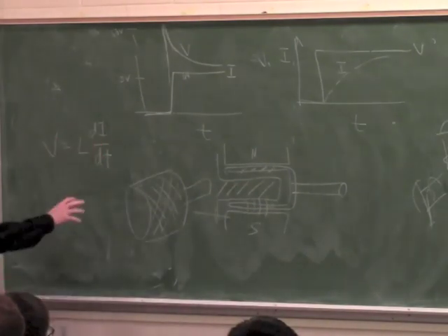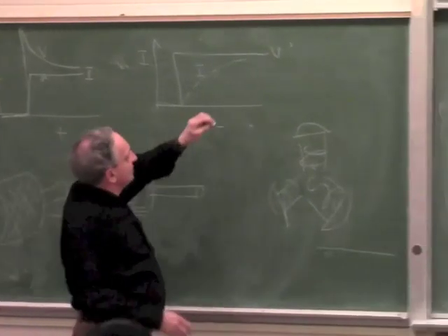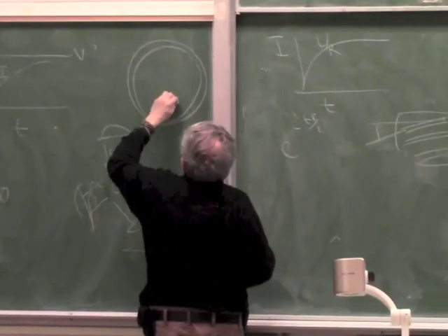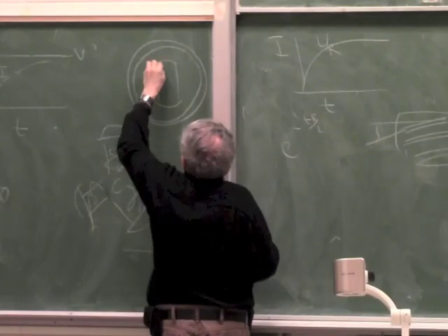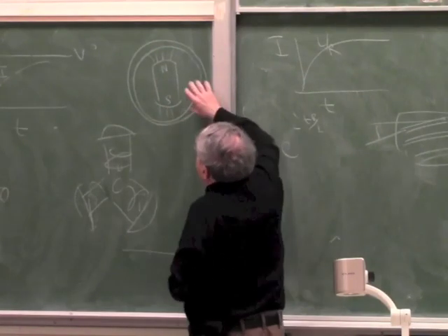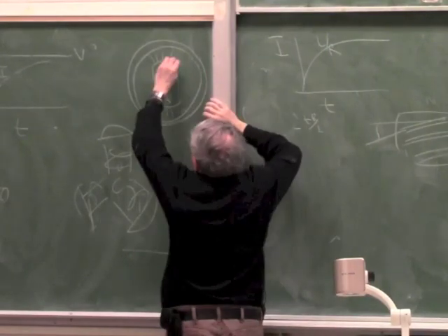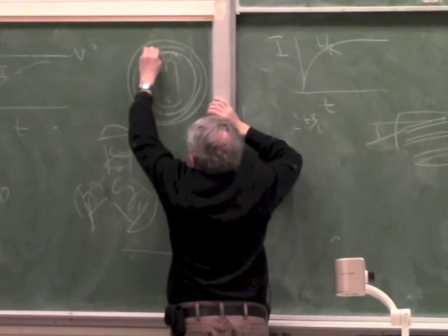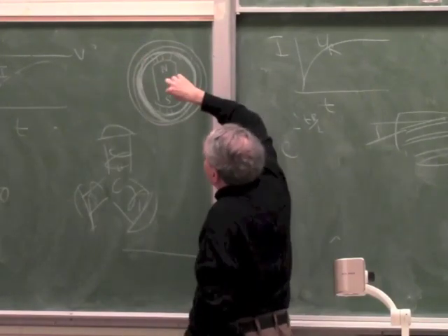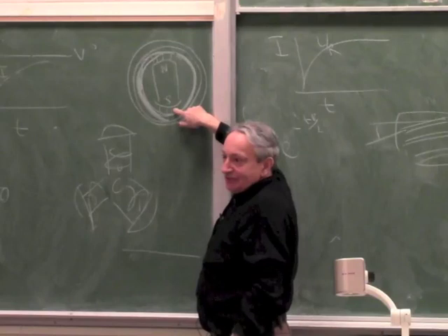Okay, so if I look at this motor from this side, what I see is I'll draw it here. I see a steel ring which is just to close the magnetic flux. Now I see a permanent magnet which is sitting inside and closes the flux to the steel, but this magnet doesn't rotate. And then I have a cup which goes in here. So this is a cup, okay, and this cup has a winding on it and has a shaft from one side, and it rotates in the air gap.